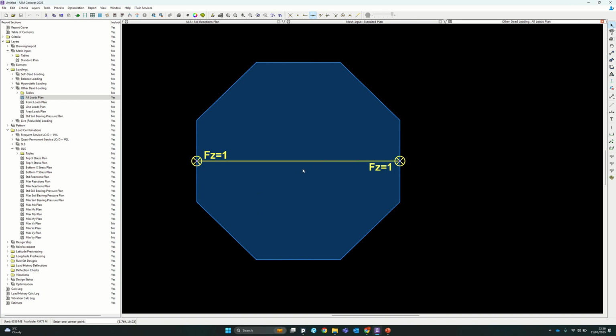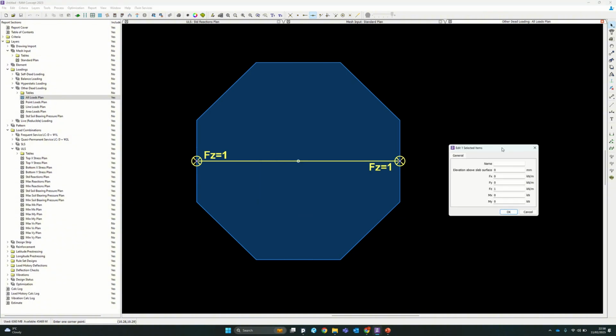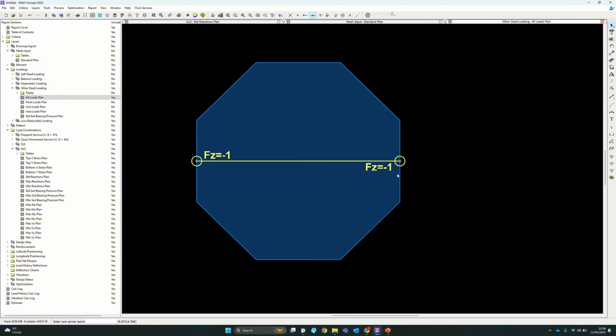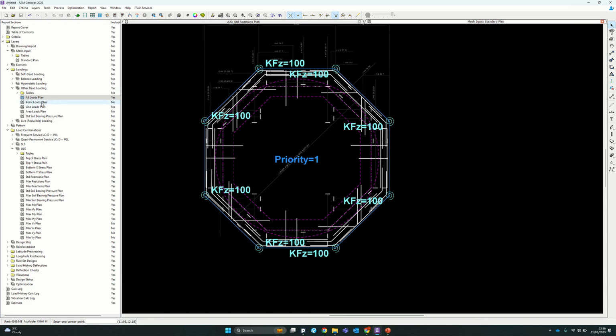So as I just did then, if you just right click while something is highlighted, select properties, you can get up whatever properties you're clicking. So if we change these to minus numbers, obviously it's going the opposite direction, isn't it? And if we go through and rerun it, hopefully that will have fixed the problems.